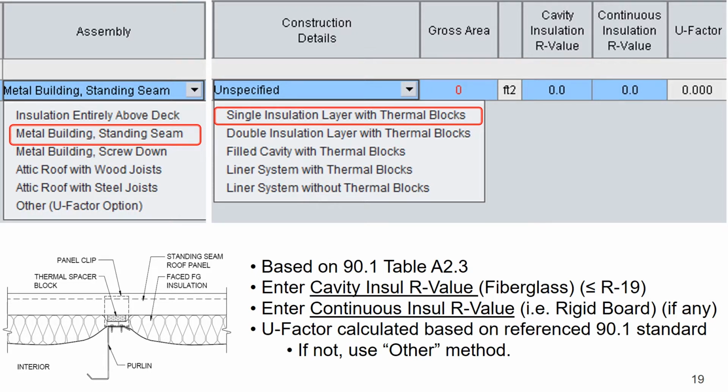So for this case, it would probably enter in a 0.082 for the U factor based off of the 2013 version of ASHRAE standard 90.1 because I selected the 2015 IECC. This version of the IECC would point back to the reference version of 90.1.